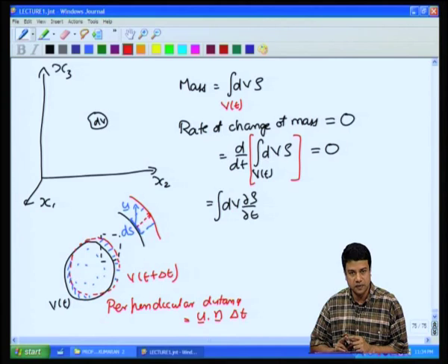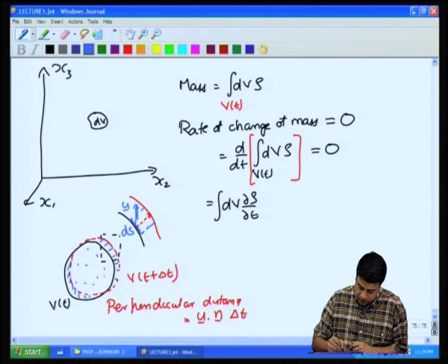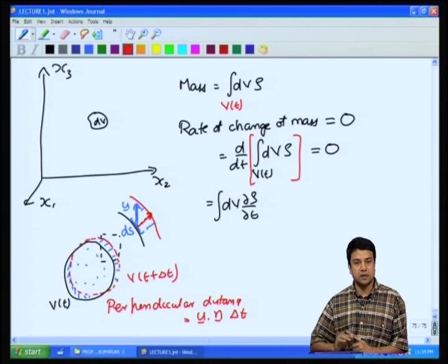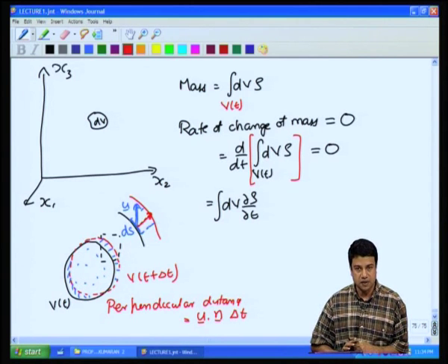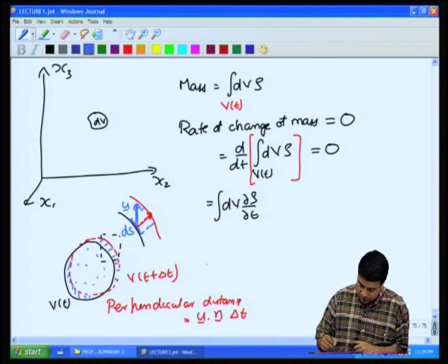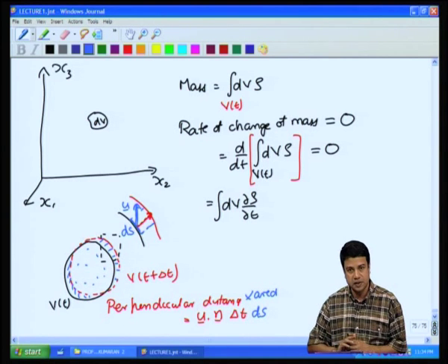Note that u dot n is a velocity, the normal velocity. It is the component of the velocity u along the unit normal to the surface n. Note that this is the outward unit normal to the surface. So, that is the distance travelled. The total volume that has come in is equal to the distance travelled times that surface patch area. So, the volume that has come in is this times ds. So, there is a total volume that has come in because the surface has travelled.